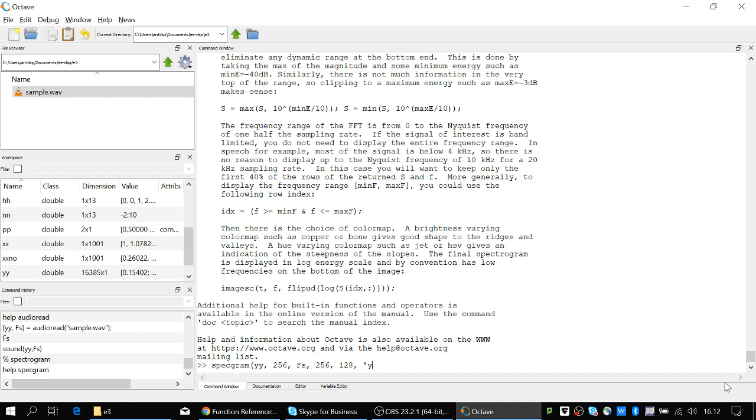And next one is very important for MATLAB, especially the spectrogram should plot the frequency on y-axis. Otherwise, the default is it will put the frequency on this spectrogram on x-axis and time on y-axis. It's really awkward. This is what you get when you give a mathematician a job to do some subroutines for engineers.